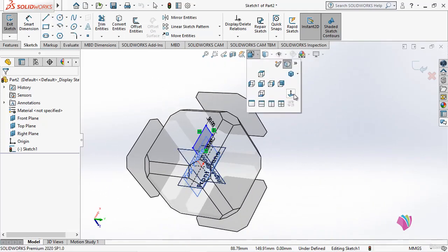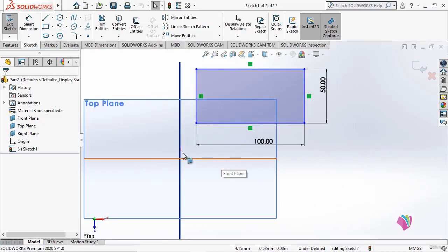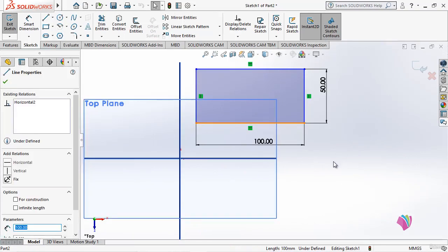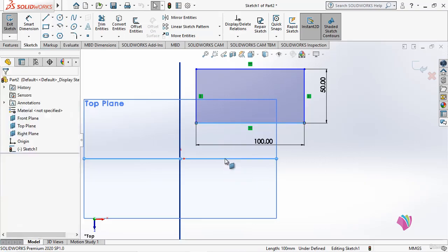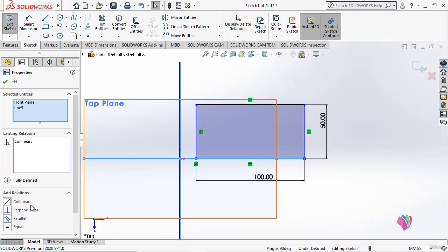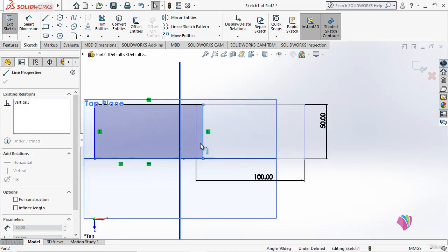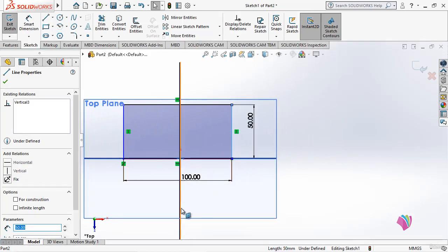Now we'll select here and use plane normal. We have our axis now. We can use this as an axis and this as an axis. And of course in this plane we are now working. We'll select this line, use the control button for multiple selection and use this plane which will act as an axis. And of both of these, what we want to do? We want to create a collinearity between them. Press the escape key to exit from the command.